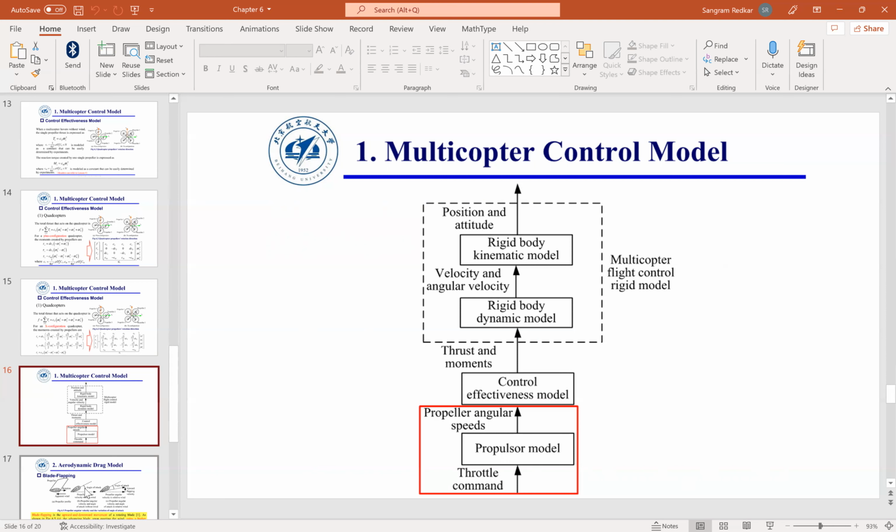But in addition to that, if you look at the prop, as the prop is rotating, there is a trailing edge and there is a leading edge. Initially, as the prop is going forward, it is increasing the speed. As the prop is going backward, it is decreasing the speed, depending upon whether the aircraft is moving forward or backward. So this differential speed causes something called blade flapping.